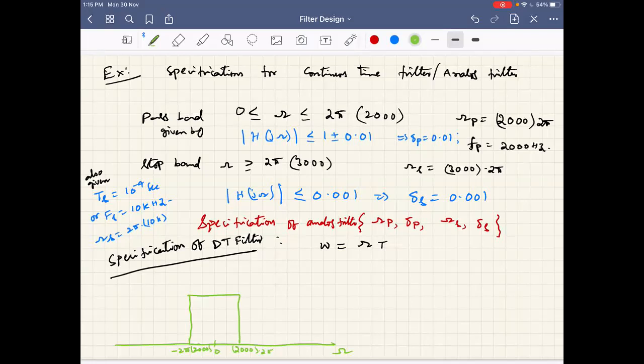to get the discrete signal with fs equal to 10 kilohertz, where do you think it repeats? It repeats at 10 kilohertz. So this is 2, 4, 6, 8, and 10. Okay, so it repeats again here, right? And this is roughly 5 kilohertz. This is 5 kilohertz.